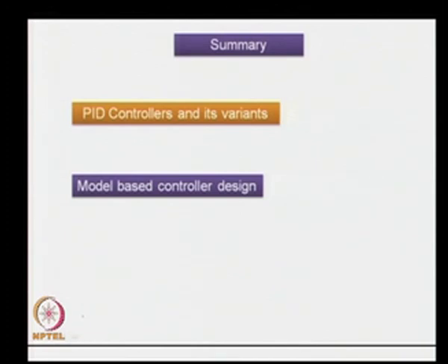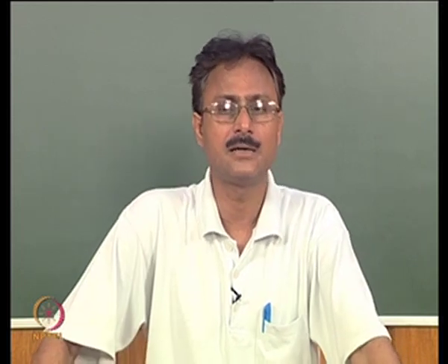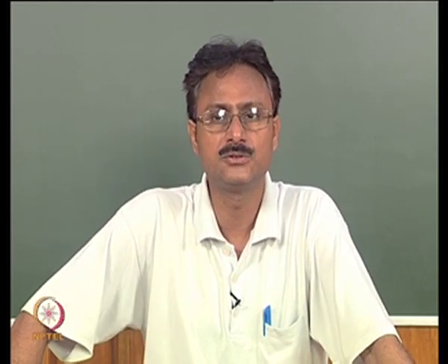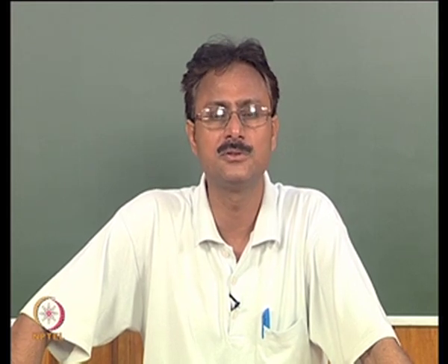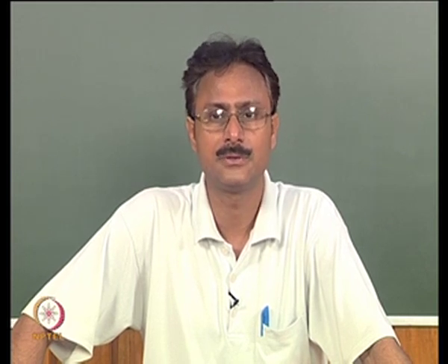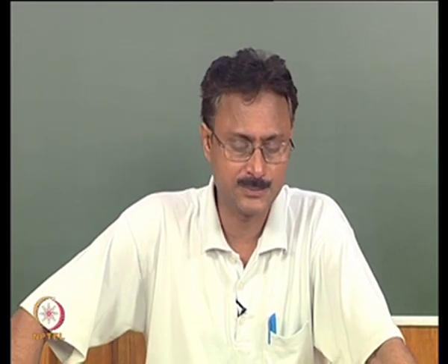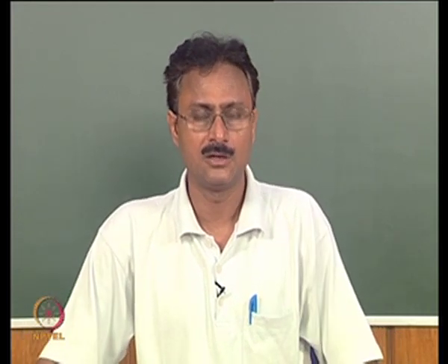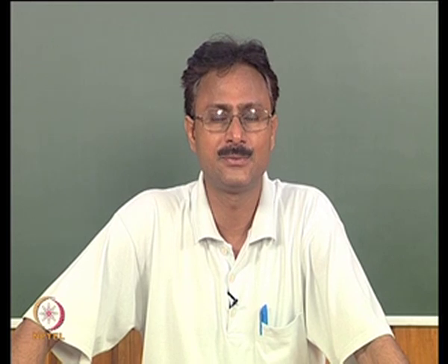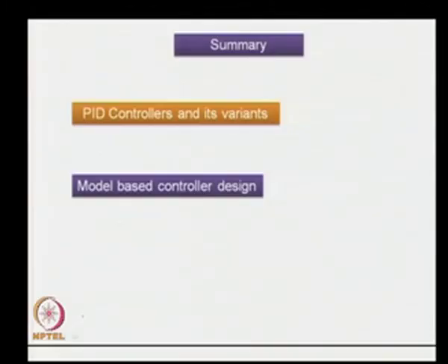Let me summarize this lecture. PID controllers and its variants have been discussed. We have found that with the use of positive feedback, it is possible to overcome the integral windup phenomenon often encountered in practice. Similarly, with the use of derivative filter, it is possible to overcome the derivative kick phenomenon associated with a controller.